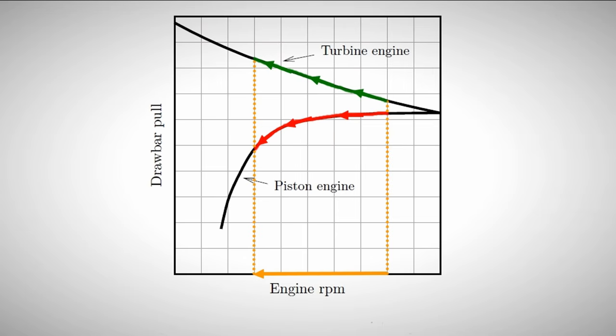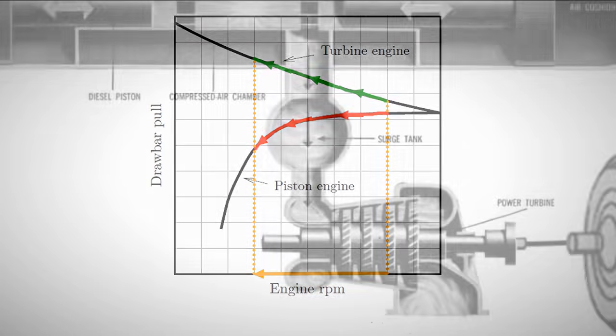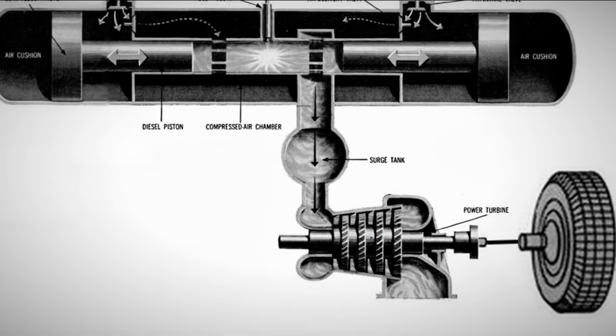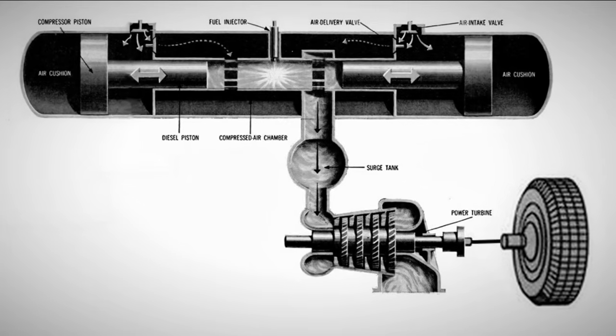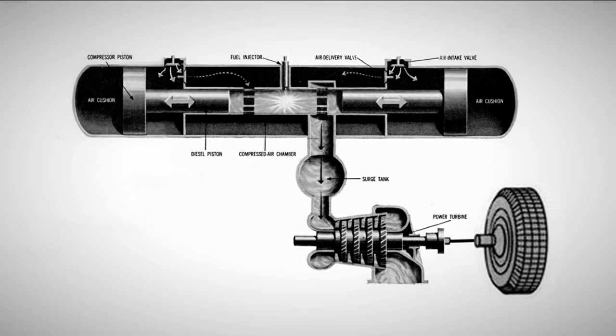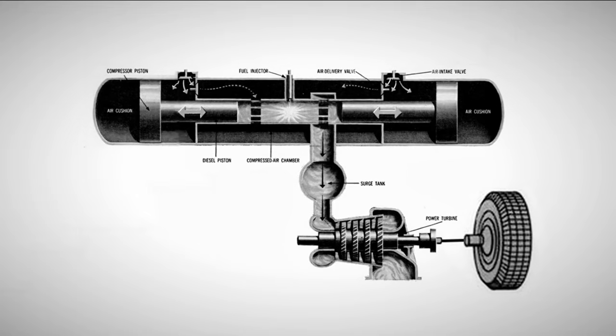This is because tractors with conventional diesel engines had a torque reserve of 12 to 15%, while gas turbo engines had a torque reserve of 250 to 300%. The absence of a rigid mechanical connection between the gas generator and the gas turbine ensured smooth torque changes. This reduced wheel or track slippage, which should have increased the tractor's productivity.